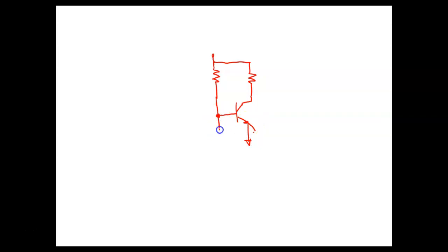See, this is done a lot. So with the switch open, you put 0 volts on the base, and the transistor would turn off. When you close the switch, then we would have bias, but here we wouldn't calculate it for 2 voltages. If this was 15 volts, then we'd have to choose that resistor here to drop 14.3 volts.